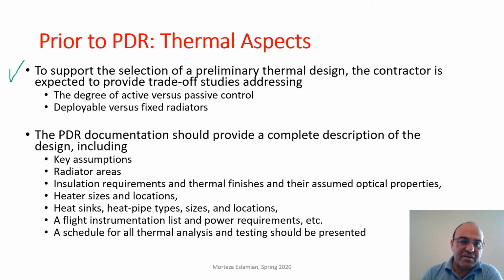Also, if the contractor wants to use deployable radiators versus fixed radiators, they need to provide trade-off studies to demonstrate the need for deployable radiators. Deployable radiators, if you remember, are the radiators which are unfolded. So of course they are actuated. There is a higher risk of failure. So if needed, then it has to be proven that they are needed.